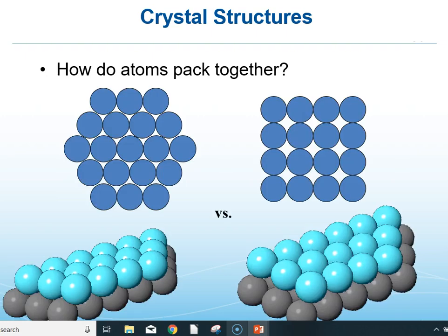So you can see we've got two different variations here. Over on the left you have what we would call a close packed structure. If you assume that those are atoms and you're looking down on a sectioned plane of atoms all packed together, and you can see the 3D version down below, for equally sized atoms, of equal radius, you've got literally as many atoms as you can pack around one as can be achieved. This is called close pack configuration or circle packing.